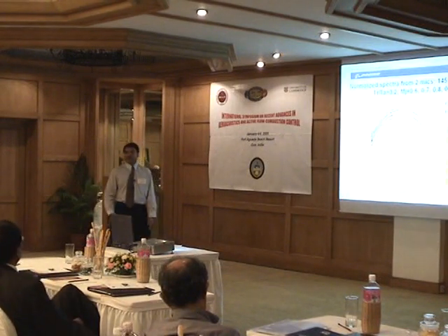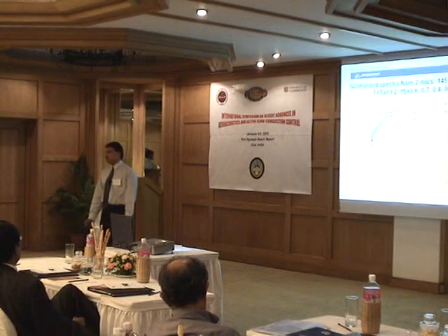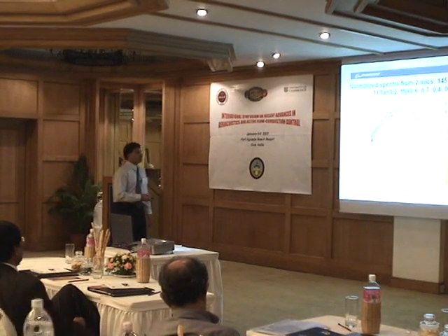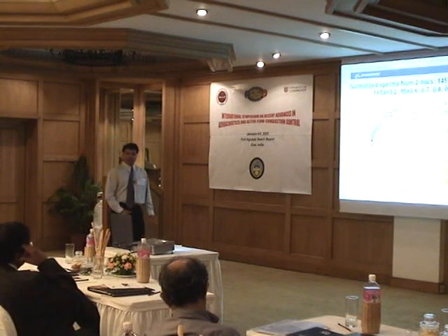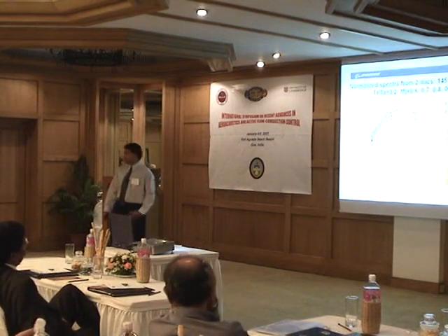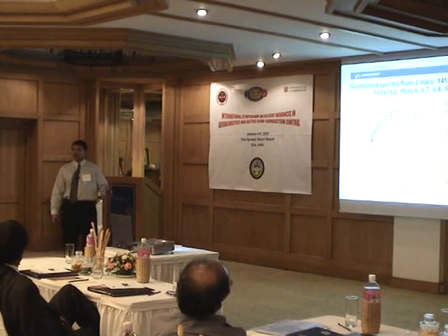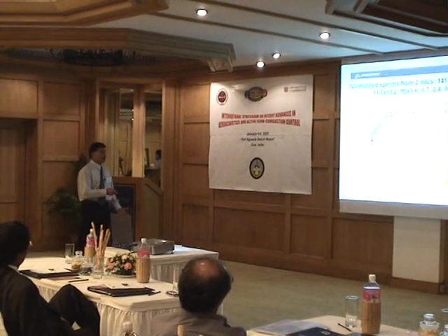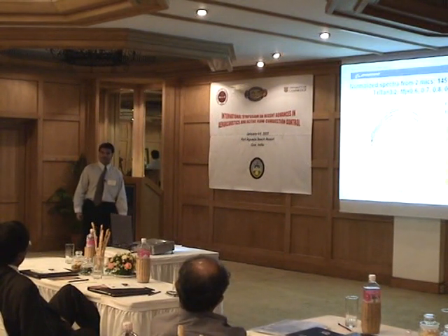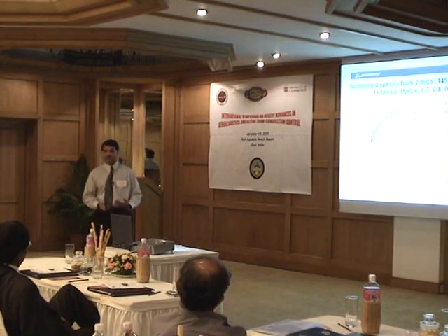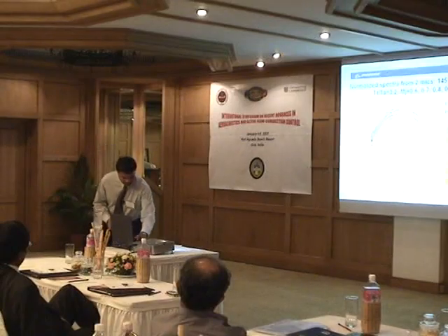Now, it's been traditionally believed that you need to have a very high amplitude to have nonlinear propagation. And this is the overall sound pressure level measured at a distance of 78 diameters and starts at 110 dB for the lowest Mach number case. And there is not a big jump of only 4 dB between when you change the jet Mach number from 0.8 to 0.9. So I want to propose that somehow the nonlinear propagation doesn't seem to be tied to very high amplitudes, but it is well represented or well quantified by the convective Mach number for jets, which is totally unexpected, and this is some of the reasons why we're having problems trying to collapse model data with engine data, which I'll address in a future conference.